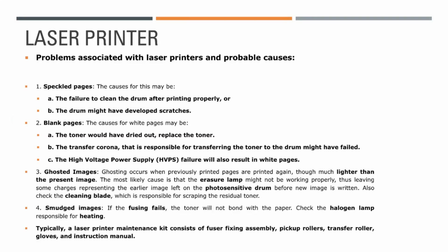Laser printer problems associated with laser printers and probable causes. Speckled pages. The cause for this may be a failure to clean the drum after printing, or the drum might have developed scratches. Blank pages. The causes for white pages may be that the toner has dried out, so replace the toner. The transfer corona that is responsible for transferring the toner to the drum might have failed. The high voltage power supply, HVPS, failure will also result in white pages.